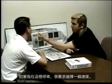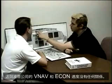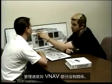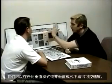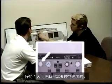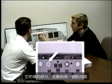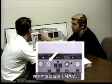If I pull here, I'm asking for a selected speed. Okay? It has no relationship to, like, the Boeings have this VNAV and the econ speed. There's no relationship of managed speed to the VNAV portion. We can get managed speed in any vertical mode or no vertical mode whatsoever. Okay? So pushing is a managed speed, pulling is a selected speed. With the lateral portion of it, pulling is giving me a heading or a track if I'm in track flight path angle. Pushing it is asking for LNAV.